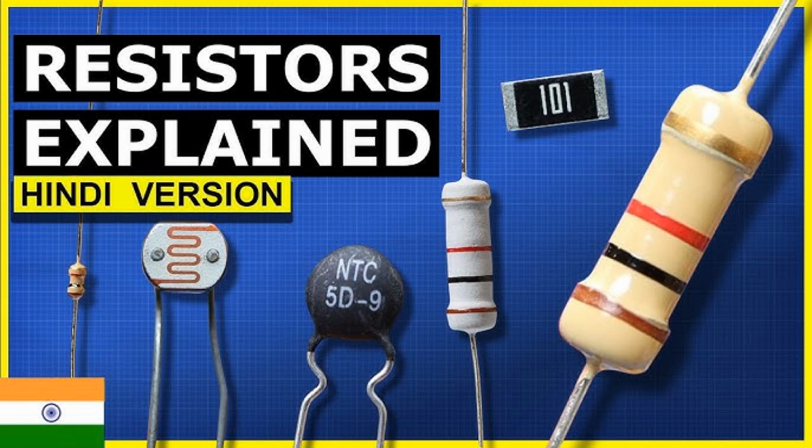A microcontroller input pin might have a pull-down resistor to ensure it reads low when not connected, preventing false high readings due to noise or leakage currents. Communication lines. Purpose. In communication protocols like I2C, pull-up resistors are essential to ensure that data and clock lines are correctly biased when no device is actively driving them.